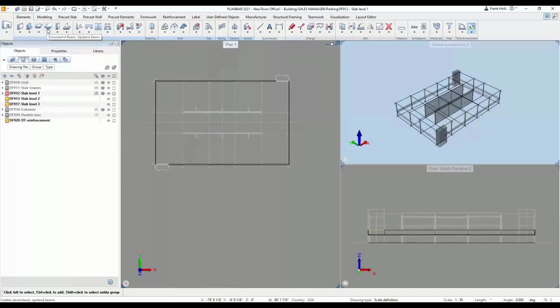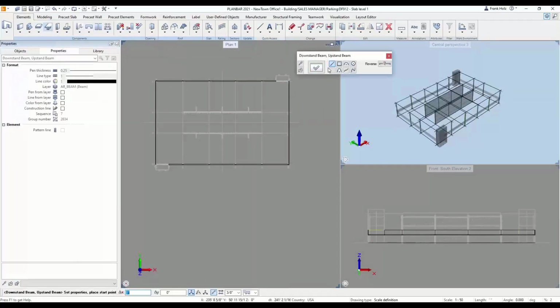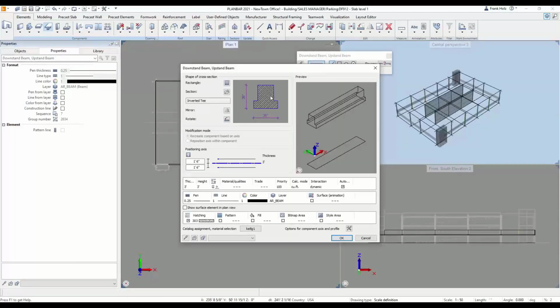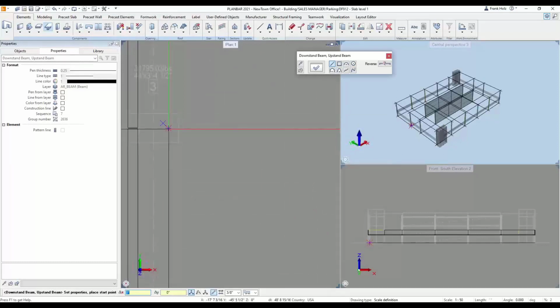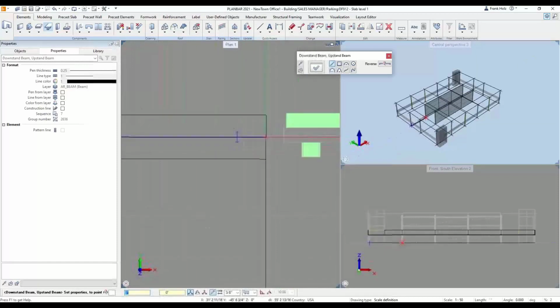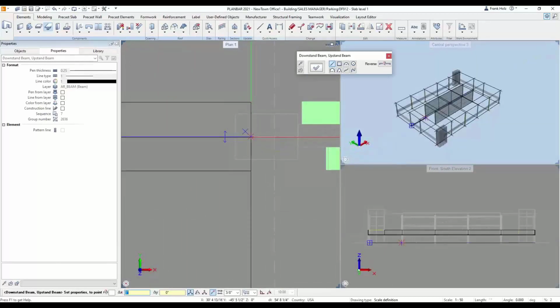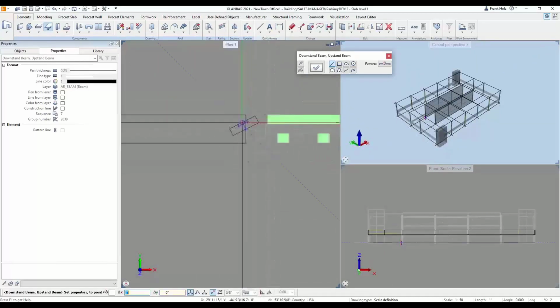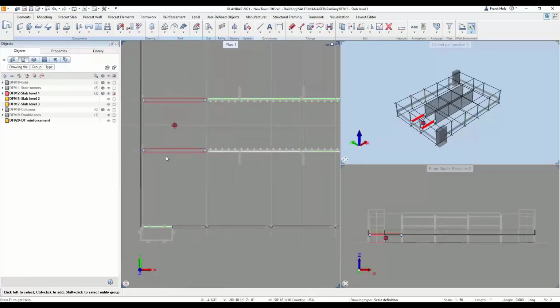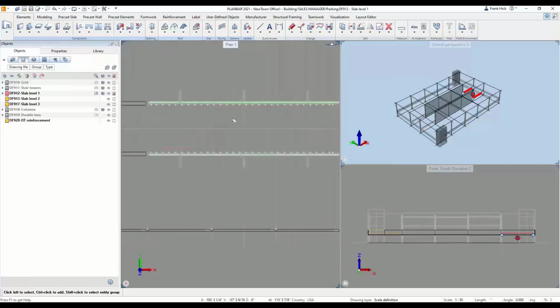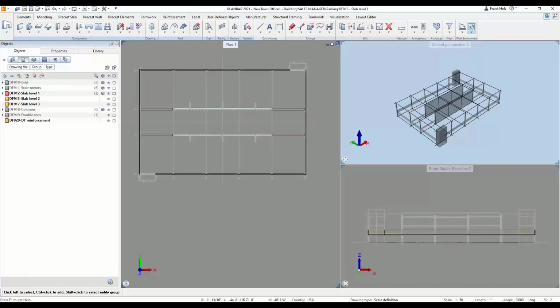And now I'm going to complete out this first floor with my beam. As before, I select a profile, a height, and it's just as simple as coming down to my column. I'm going to create a 3/4 inch joint, draw from one column to the other, and again, do a 3/4 inch joint. Now it's just like any other CAD operation. I can use my copy routine, copy it down to my other beam line, and finally, I'll use a mirror since they are symmetric to bring it over to the other side here.